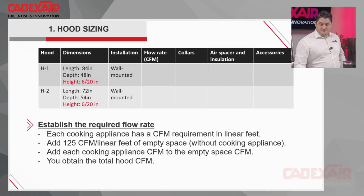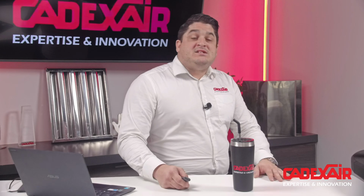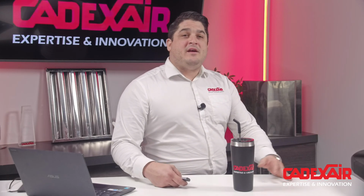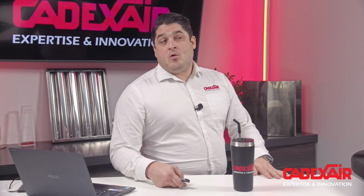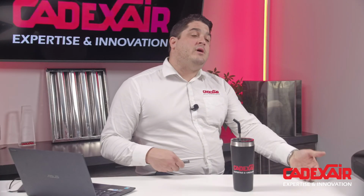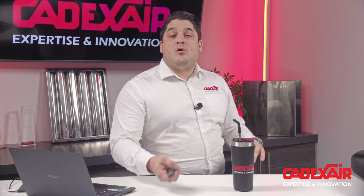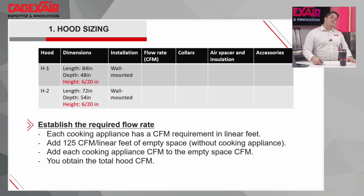Okay, so now that we've determined the dimension of the hood, how do we choose my fan and the airflow that I require for all of my cooking appliances? Yeah. I will say all kitchen manufacturers probably have their ways, but I think it's almost all similar. We work with charts that use a CFM per type of equipment. If it's electric or gas, it will take less or more. At Cadexair, we choose to put 125 CFM per linear foot when there's empty space.